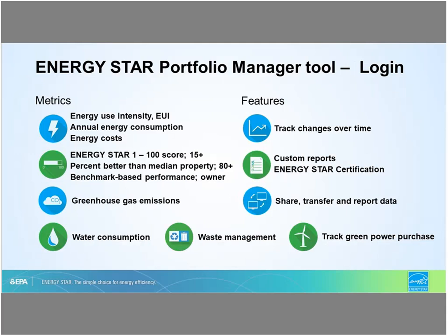And again, you can use it to track energy over time. And here, this is one that's probably not on any of the other slides about benchmarking, and that's benchmark-based performance targets. I put that one in because, like the chart that I showed earlier, you can use the tool to set up a group of properties, group those properties, download them into an Excel spreadsheet, look at their EUIs, and use that as a way of setting a meaningful target for your buildings.